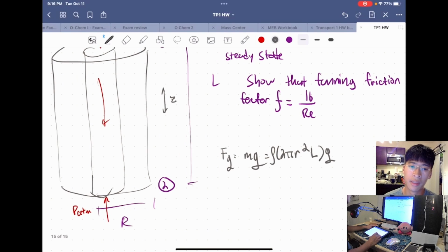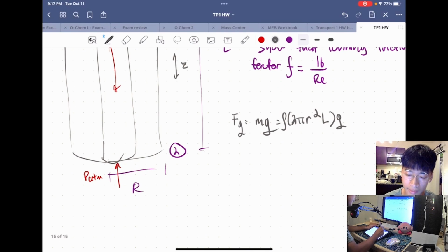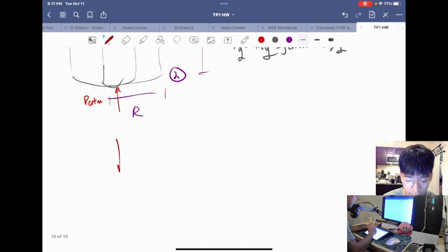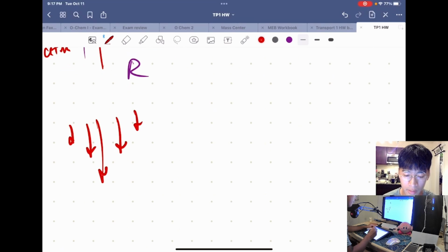And we consider, no, it's not our only force, because let's focus on the idea of this typical velocity profile for a cylindrical pipe. It looks something like this, right? And what you notice is that for the fluid in the center, okay, for laminar flow, it's the fastest, right? And its neighbors are not so fast. And how are its neighbors gaining its velocity? Well, it's gaining it by this boundary in the middle, dragging its neighbors along.